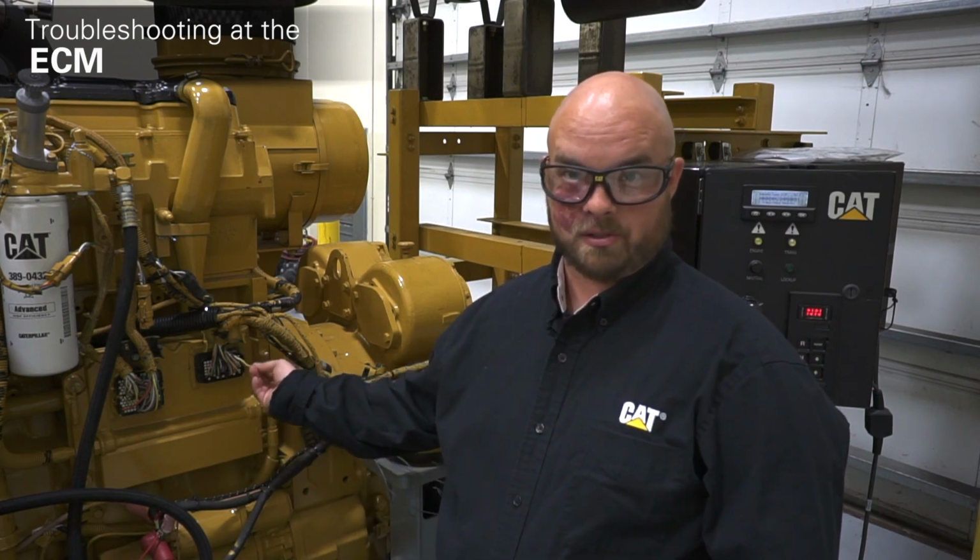Okay, so let's back up a step and change the scenario. I made the open circuit at my ECM, and again, I wait my debounce time. And I wait, but yet I still have a -4 voltage below normal code, even though I've created an open circuit condition. Now in that scenario, it tells me that the ECM is not recognizing that I'm making this open circuit. It's telling me there's still a short circuit somewhere, and now we've gone as far as we can go. The ECM at this point, somewhere internally, has a short circuit condition, and we're going to go through our ECM replacement procedure.